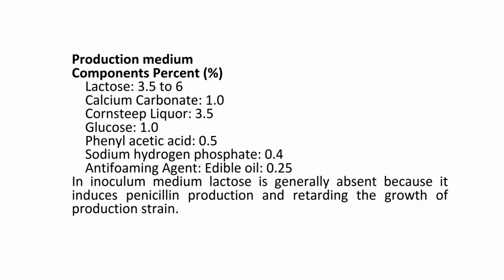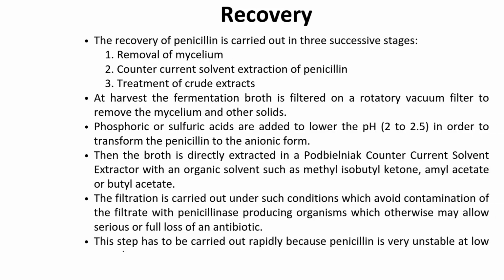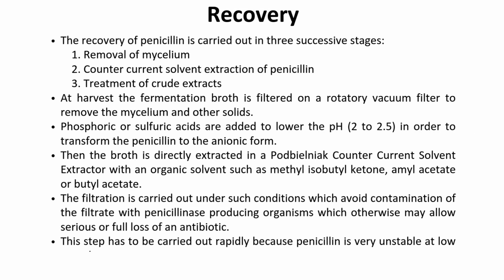It's important to note that lactose is generally absent in the inoculum medium because it induces penicillin production, but can retard the growth of the production strain. Moving on, we explore the recovery process. The recovery of penicillin is carried out in 3 successive stages: removal of the mycelium, countercurrent solvent extraction of penicillin, and treatment of crude extracts.